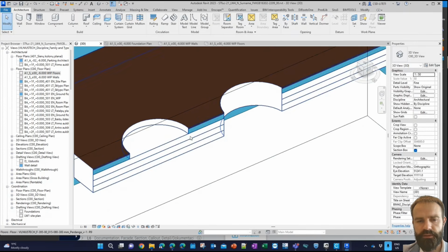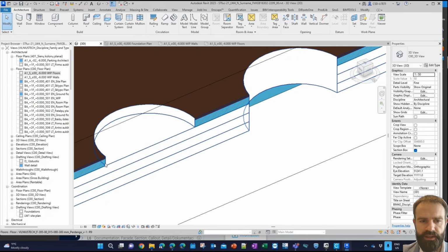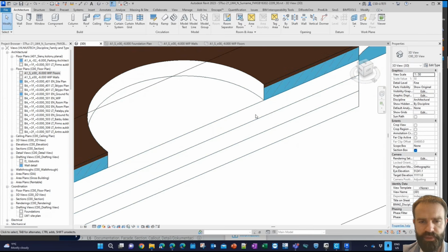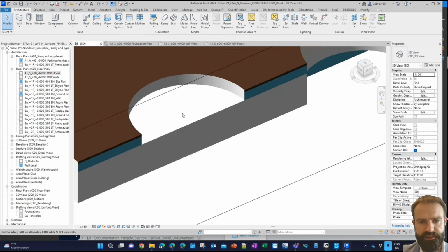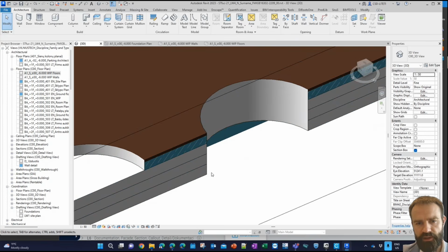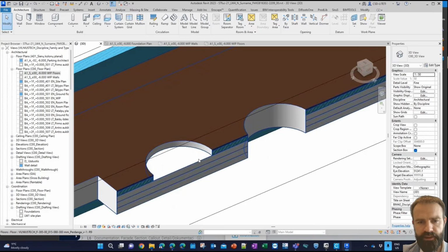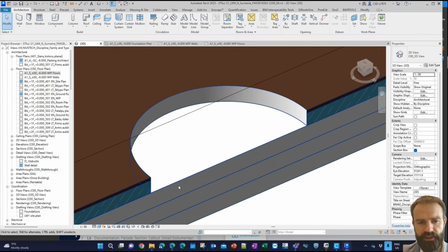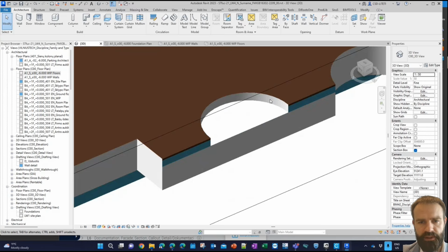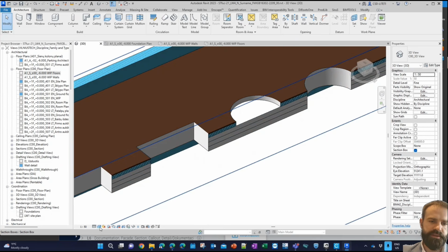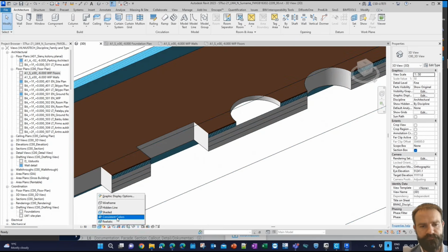And if I use this special tool or special family, it creates just an opening inside the element. So if I put shadings, here you can see one is cutting through all the layers and another is making a cut inside the floor. So sometimes it needs to be done like that.